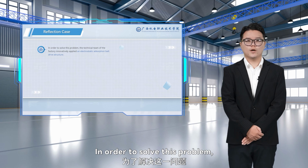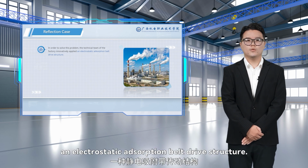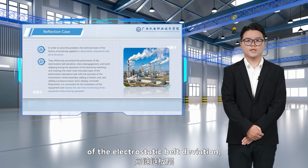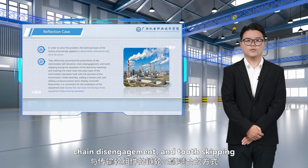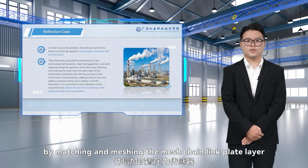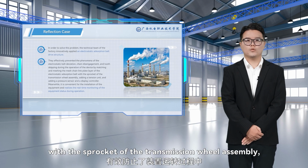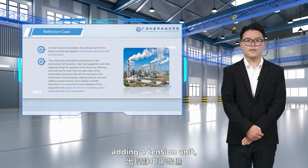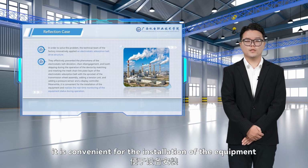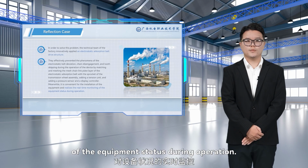In order to solve this problem, the technical team of the factory innovatively applied an electrostatic adsorption belt drive structure. They effectively prevented the phenomena of the electrostatic belt deviation, chain disengagement, and tooth skipping during the operation of the device by matching and meshing the mesh chain link plate layer of the electrostatic adsorption belt with the sprocket of the transmission wheel assembly, adding a tension unit, and adding a pressure sensor and a display controller.